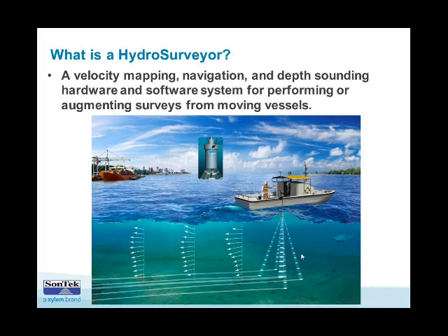And the schematic here gives an overview. Here we have the ADCP down below the boat, and at the same time as it's profiling the water velocity, it's also tracking the boat's movement over the bottom and getting the depths at 5 different locations at a time.